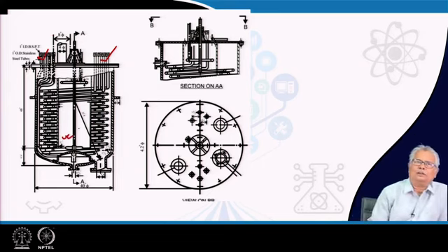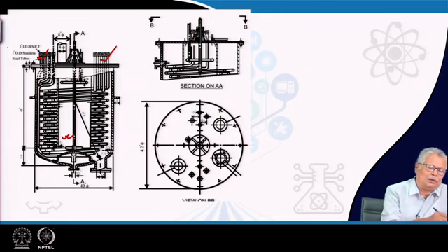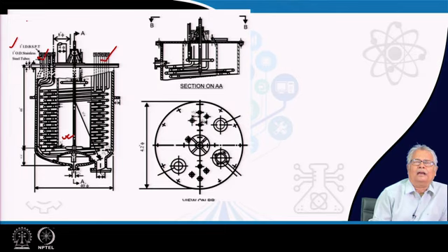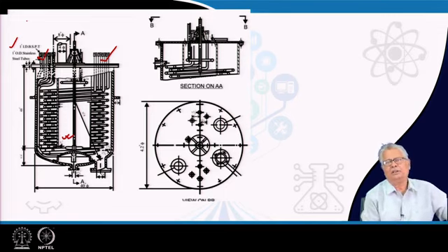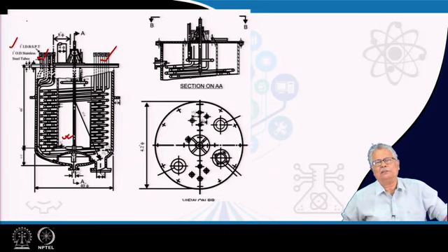If we know your heat transfer coefficient inside your tube, which you know basically because you are choosing here 1-inch OD stainless steel tubes, and that you are using for your coils, and if you are designing your coil diameters accordingly, you will definitely be in a position to estimate the total heat transfer area required for the coils and move on.